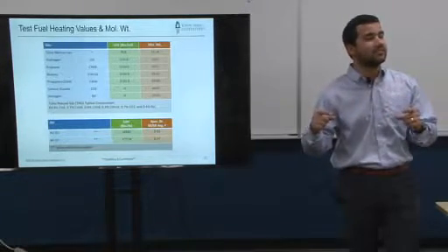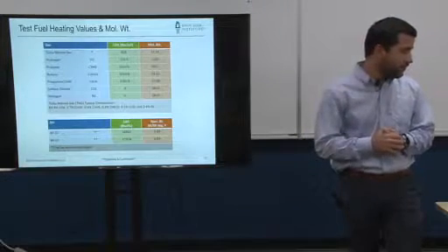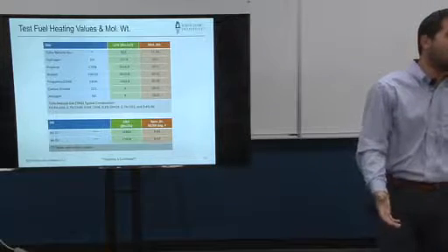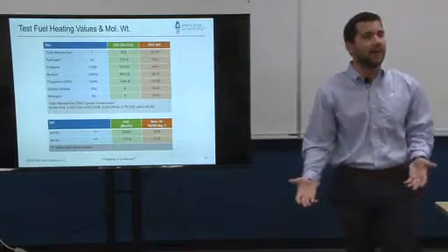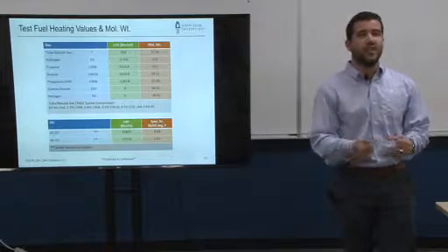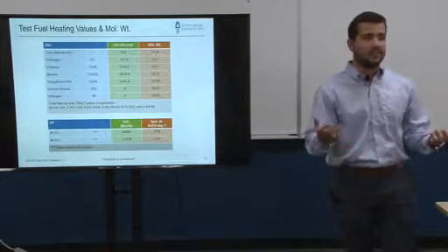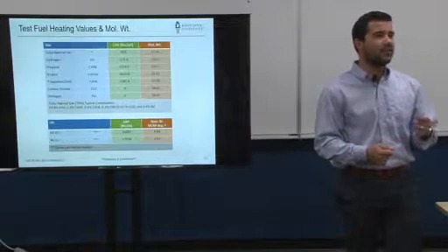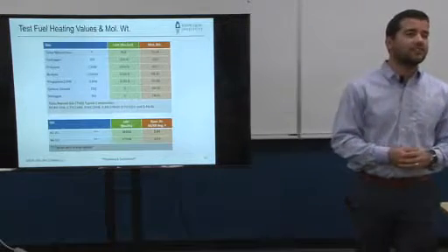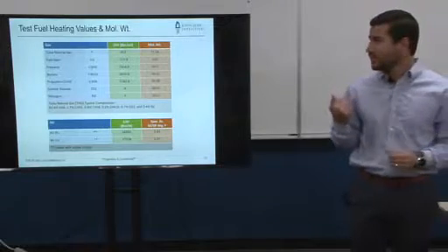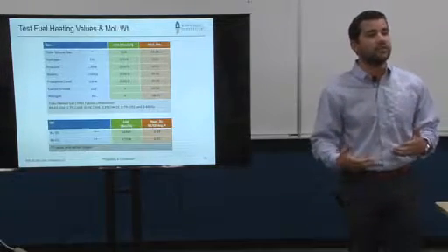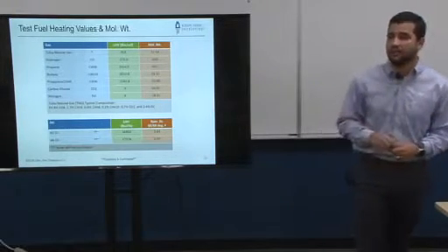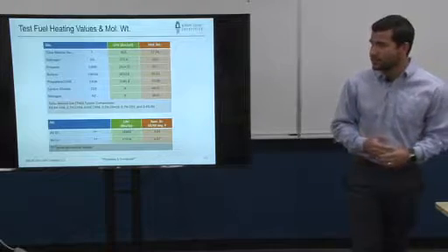expensive than natural gas. So if you think about it, sometimes when we go to lunch, we leave the burner running because we're just not going to take it down for going to lunch, right? It's about an hour there. So typically we switch to natural gas because in an hour you can spend, say, $100 just firing 10 million BTUs an hour. Well, if you did that with hydrogen, that would have been $1,000. So having little things like this in mind when you are building your test or when you are executing your test really come in handy at the time of having a successful burner test.